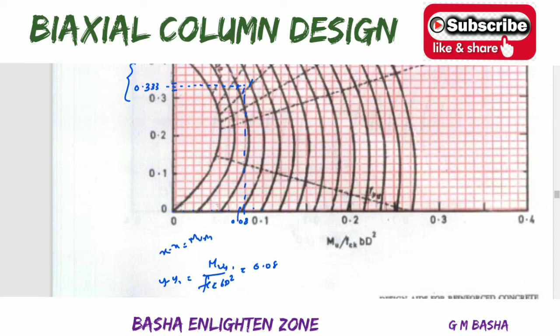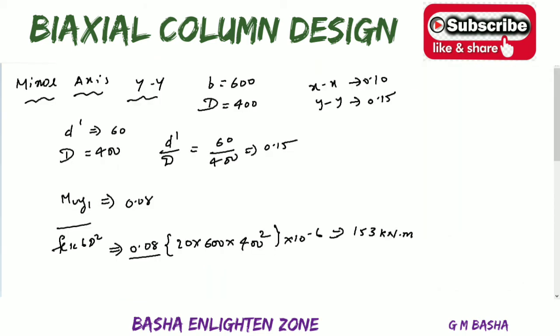Maybe you will get a difference of some 0.075 to 0.085 around, or 0.09 also sometimes. So I already calculated for 0.09. For that the moment will be equal to 173 kilonewton meter. If you solve for 0.08, the moment will be 153 kilonewton meter. However, you will get the overall value which is less than or equal to 1, as I showed in the IS code book. If you take this one also you will get less than 1 only. I checked for both the values. Then your Muy1 value will be equal to 153 kilonewton meter.